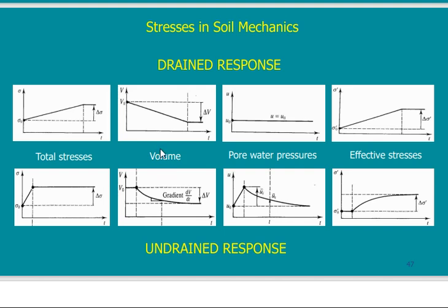So I tried my best to put it in a way that you understand all the differences, what happens in terms of the total stress, which is your load acting on the ground, what happens in terms of volume of the soil beneath you, what happens in terms of water that is next to you, to the clay, to the particles of the soil. Will it carry load or will it not carry? It will not carry load in case of drained case. It will carry load in case of undrained, but it will carry it for a while and then will leave it.